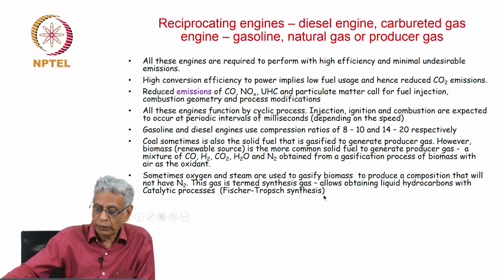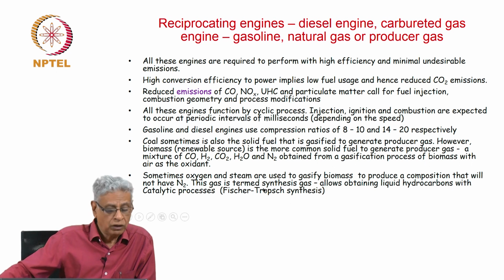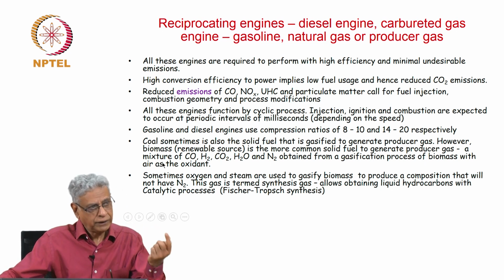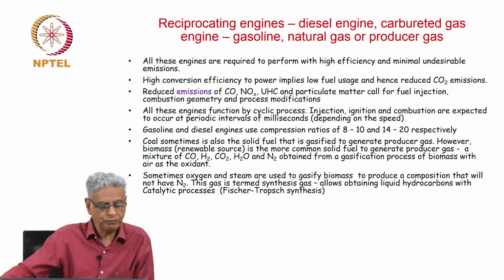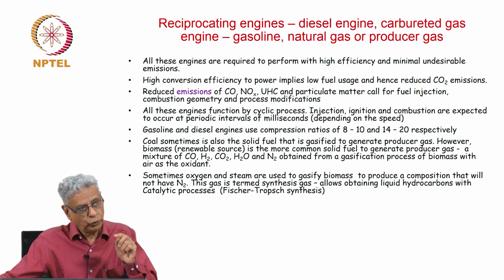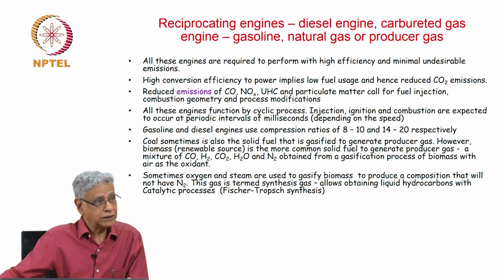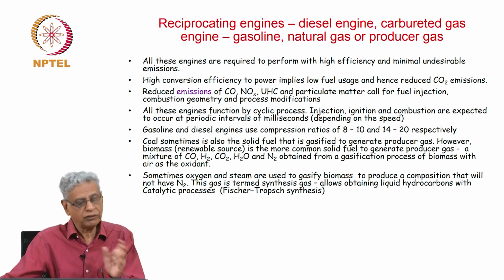It allows you to obtain liquid hydrocarbons by using catalytic processes, something called Fischer-Tropsch synthesis. I just want to tell you for clarification, those which use air as oxidant, the gas produced is called producer gas. Those which do not have nitrogen from the oxidant, you call a synthesis gas because you can use it to synthesize liquid fuels.